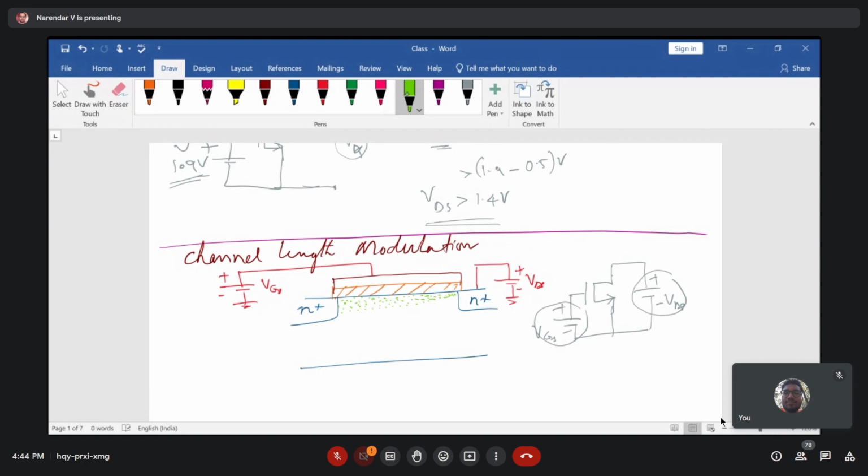The inversion layer is created by applying a gate voltage so that the opposite carrier concentration is equivalent to the bulk carrier concentration. Here your bulk region is p type, so the electron concentration must be equal to the bulk concentration.